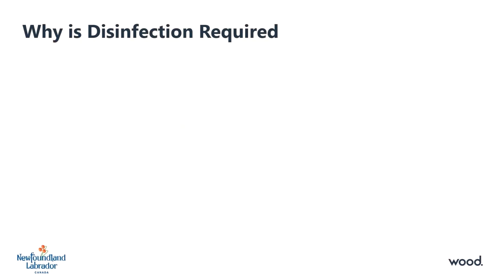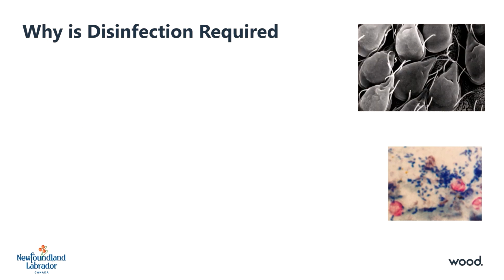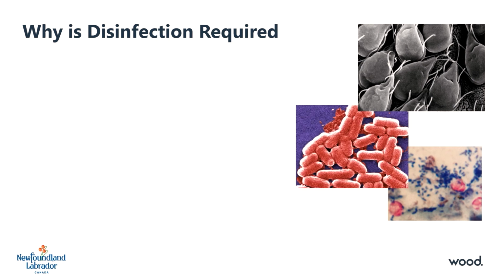Disinfection is the main tool that water operators can employ to destroy or inactivate harmful pathogens from drinking water. This is required primarily due to the health risks posed by water-borne pathogens present in source waters or that may enter the water distribution system downstream of the treatment facilities. The presence of microorganisms like Giardia and E. coli in the water supply can cause illness if the water is not effectively disinfected.